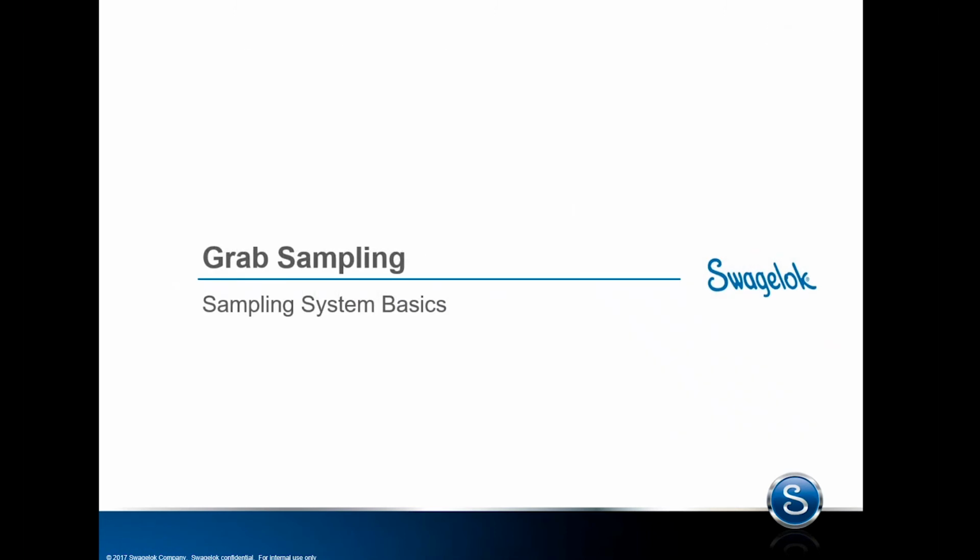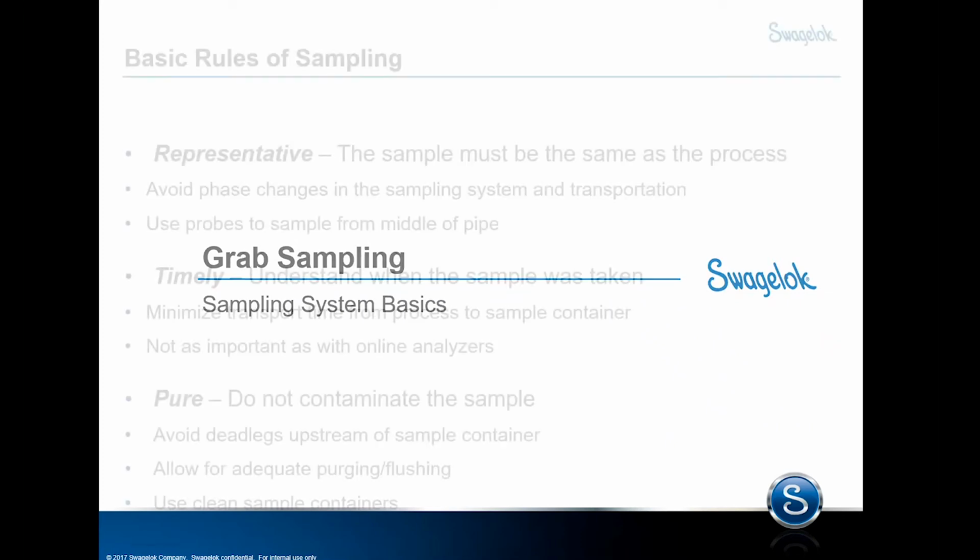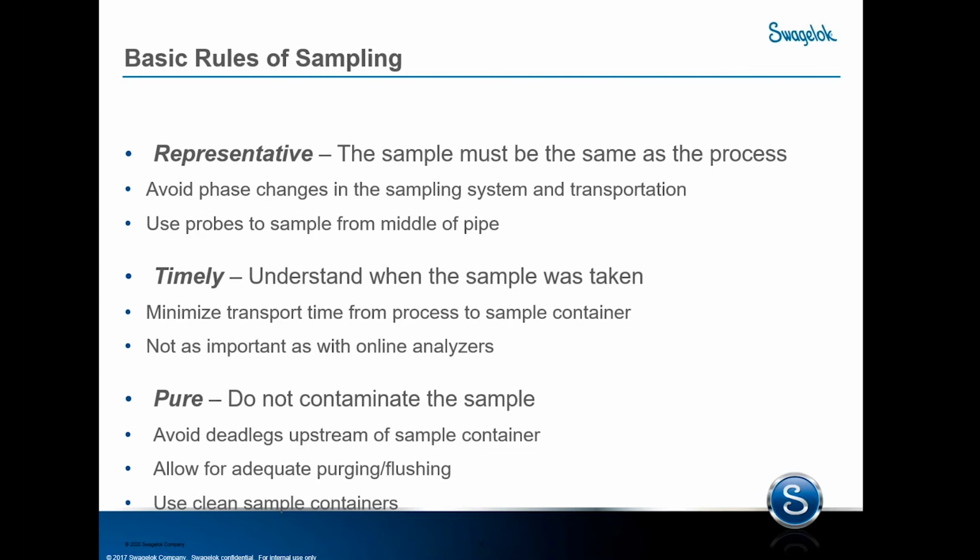Now that we have some background on grab sampling, let's discuss some of the basic principles that we use when designing a grab sampling system. So when we are designing these panels, we want to keep a number of things in mind. First of all, we want to make sure that the sample extracted from the pipeline is representative of what is actually flowing through it. As a result, the preference is to use probes so that we can sample from the